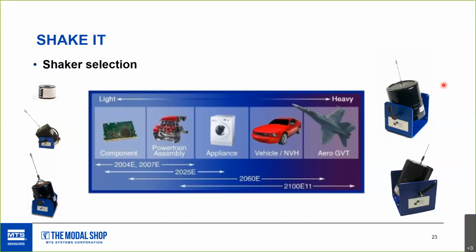Right. And then, to kind of come back to the middle where we sort of have a number of shakers we can use in your body and weight and similar type testing. This is where shakers that are sort of mid-size, like the 25E, can be great. They still offer the through-hole armature, which we'll show here in a second, discuss what its advantages are. But likewise, still have a little additional force over the smart shaker for those slightly larger items needed, while being small enough to just quickly set up relative to a larger shaker.